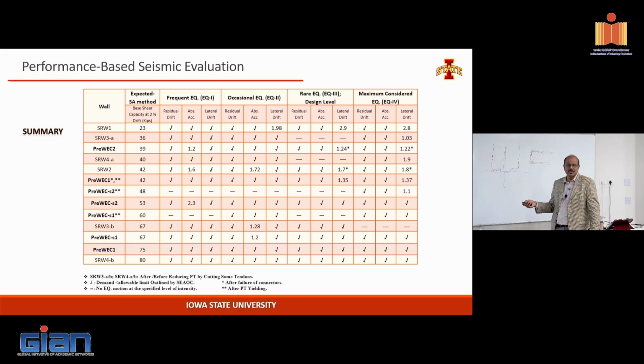But this tells you, even for non-seismic, you can actually simplify a lot of the details in terms of the amount of reinforcement and in terms of how you establish a connection. If it happens to have an earthquake, it actually will survive. Even going to low seismic, moderate seismic, you don't need anything. Look at that, this is exceeded at the maximum considered earthquake in a high seismic zone. If you're in a moderate seismic zone, I don't think you're going to go past even this. So, a really reliable system for low, moderate seismicity, fairly easy to deploy.